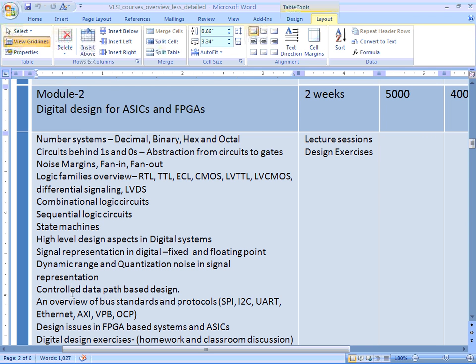When you want to implement an algorithm, finally you have to get into the RTL implementation style, register transfer level: how your data is moving from input to output among various registers, and those registers are controlled by a state machine. This is nothing but control data path. Control data path is a somewhat abstract, technically critical word which people use in algorithms. But once you understand the bits and pieces and the general implementation style of control data path design, whether the algorithm is given in C, in MATLAB, or as a paper-based design, you know how to tackle it. Your implementation will be a VLSI friendly implementation.